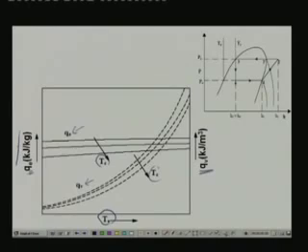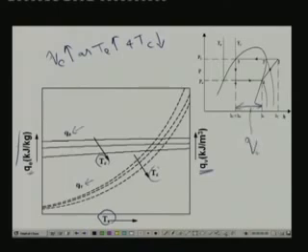That means QE increases as TE increases and TC decreases. But as I said, this effect is not very large, it is marginal. That you can easily find out from this p-h diagram. As I have already discussed in the last class, this is your refrigeration effect, or this is your QE.